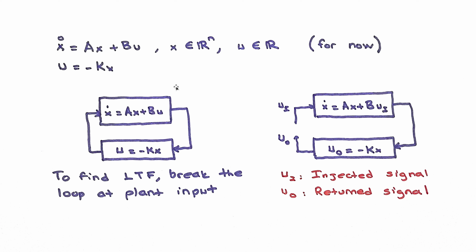All right, moving forward. Let's look at x dot equals Ax plus Bu. So x is an n-dimensional vector. u is for now just a scalar. We have one control channel for now. I would like to generalize the formulation I am making to multi-channels. And K is some control gain matrix. You can use the pole placement command or the optimal linear quadratic way to design K. Again, there are videos on my channel about those. I would like to purely focus here on stability margins.